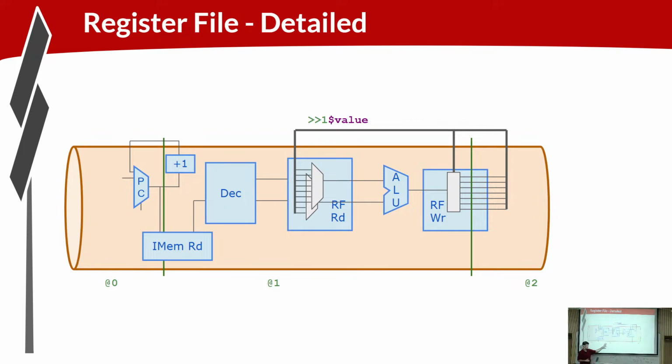It can be a little confusing at first, but when you learn to think about things this way and you map it out this way, it can avoid a lot of the careless mistakes with timing, where you're inadvertently reading the data you just wrote or something like that. So not too crazy and not too important for the simple CPU, but if you're designing an Intel class CPU, the picture gets exponentially more complex, and if you don't have a clear thought process and a framework for thinking about time, you can easily make a lot of bugs that can be hard to debug.